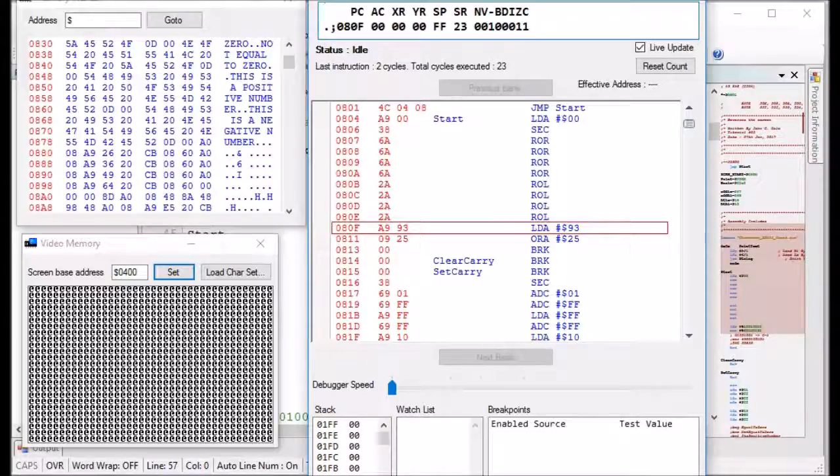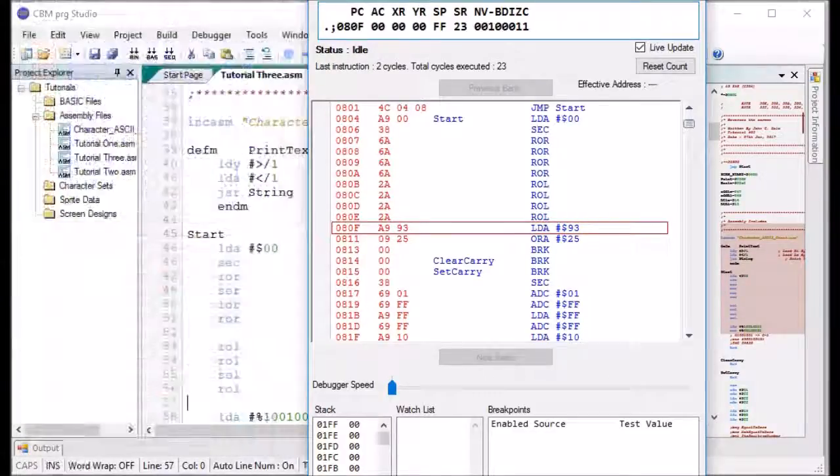It's not like the other one where it rotates one way, but it only puts a 0 in, it only injects a 0 and drops out into the carry. This is actually injecting the carry and dropping out the carry, so you could just rotate it round forever and a day.